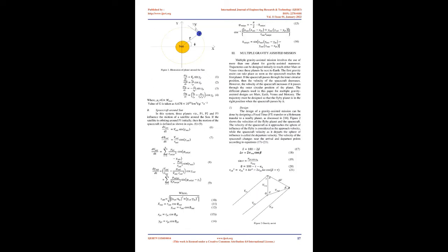the mission. Missions that used multiple gravity assists are NASA's Voyager 1 and 2, launched in 1977, Messenger, launched on August 3, 2004, etc. The BepiColombo mission of the European Space Agency is supposed to have 8 flybys around Earth, Venus, and Mercury. The gravity assist techniques are often accompanied by the use of solar sails or solar electric propulsion techniques in their mission. Low thrust and multiple gravity assist trajectories have also been designed for Mercury in 2011.